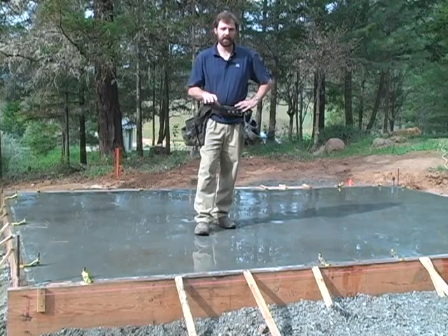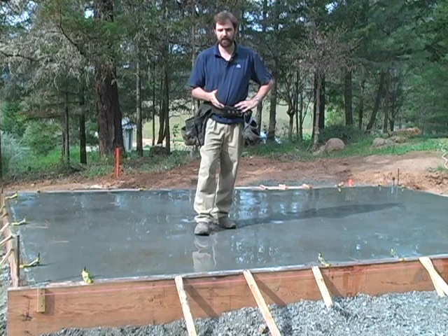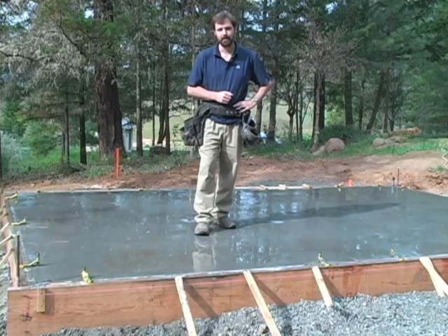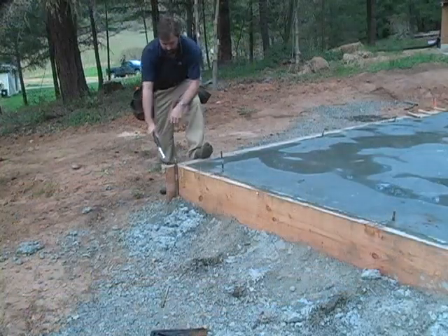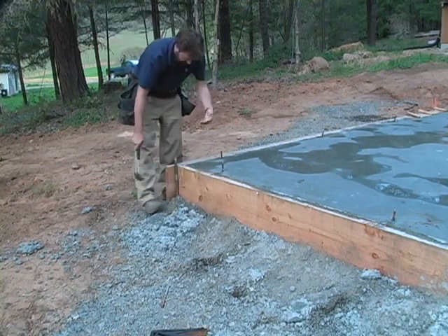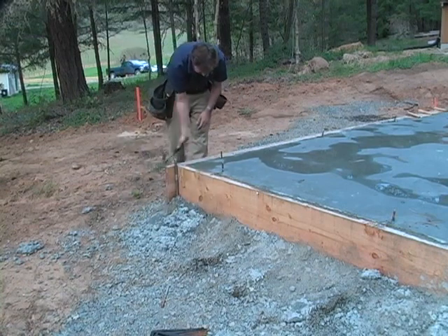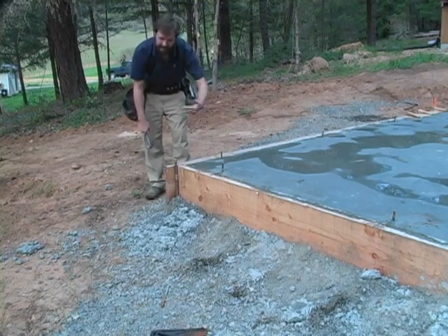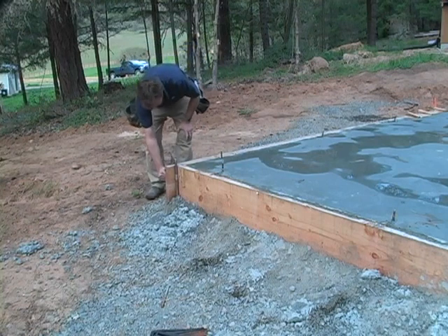It's been about 3 weeks since we poured the slab, and now that's enough time for the concrete to cure properly. So now we're ready to go around and pull off the anchor mates and take off the forms. Now when we pull the form boards off, you just give them a little whack just to loosen them up in case they're still tight against the concrete. The concrete will have shrunk just a little bit in its curing process, so it's probably pulled away from the form boards in most places.